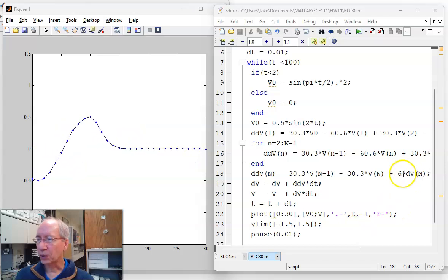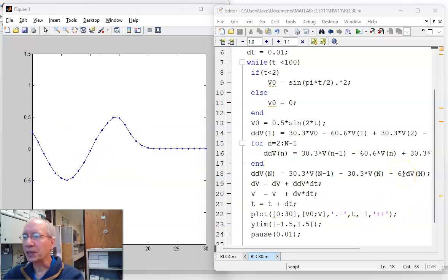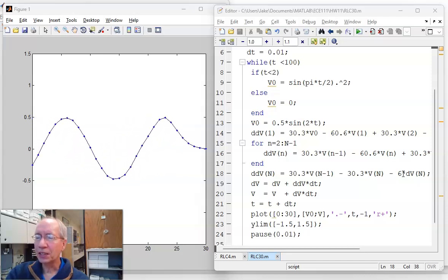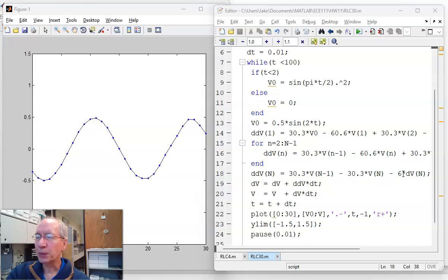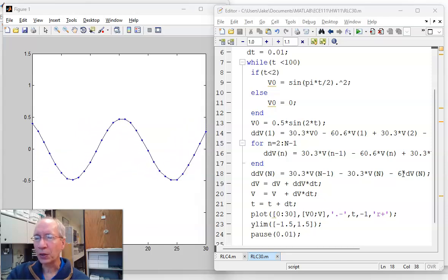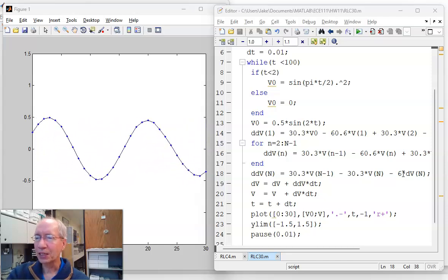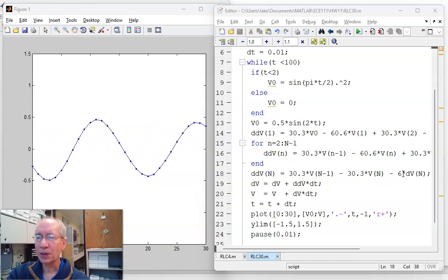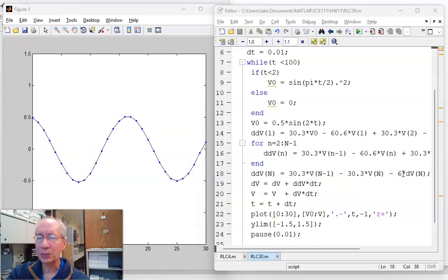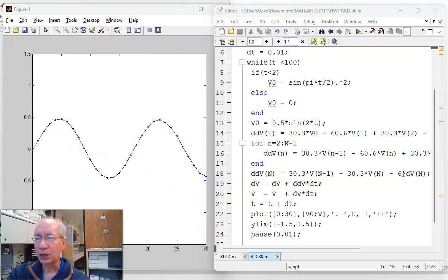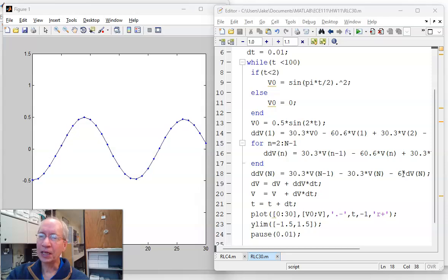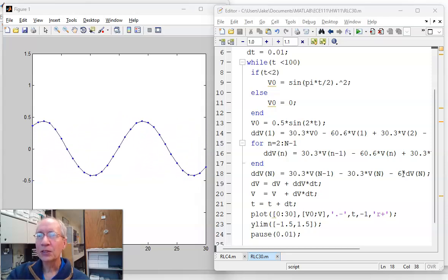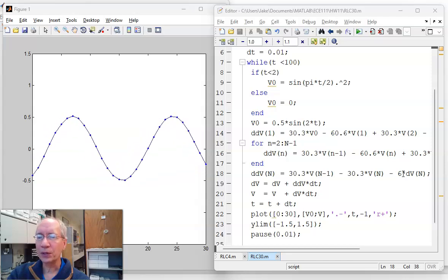If we go back to that Goldilocks number, 6 seems about the right number to get rid of reflections. If there's no reflections, then there's no standing waves. So this would be much better. This would be a bridge, walkway, stuff like that. That's not getting these huge standing waves on it that cause the metal fatigue. I just have the small amplitude input going down, hits the right side. The energy is absorbed in that resistor. So that is homework set number 11 for ECE 111.